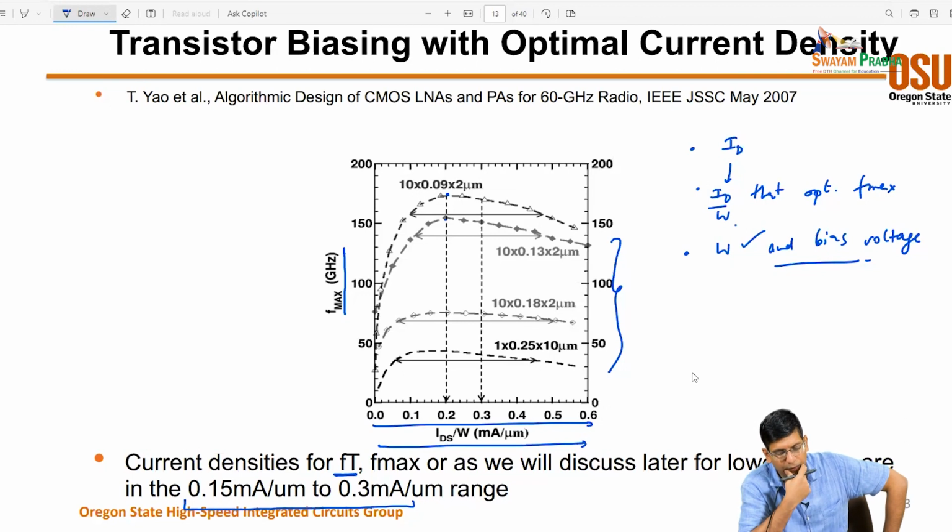when optimizing? For PA designs, usually at millimeter wave, you are starved for gain. So you are trying to bias close to Fmax anyway in order to get enough gain from the device. But once you are there, I wouldn't say that thermal considerations impact the width per finger, the current density that you use. I wouldn't say that's true.